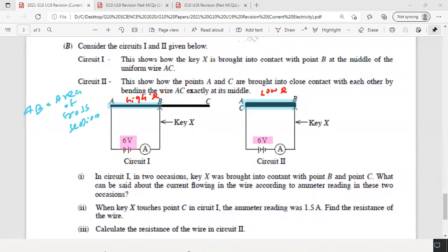When the length increases, resistance increases. Then the reading will decrease further. At B also the reading is a bit lower than in the second one. The second circuit is highest. Why? Short wire and thick wire, low resistance. Right, everyone? Long thin wire, high resistance.